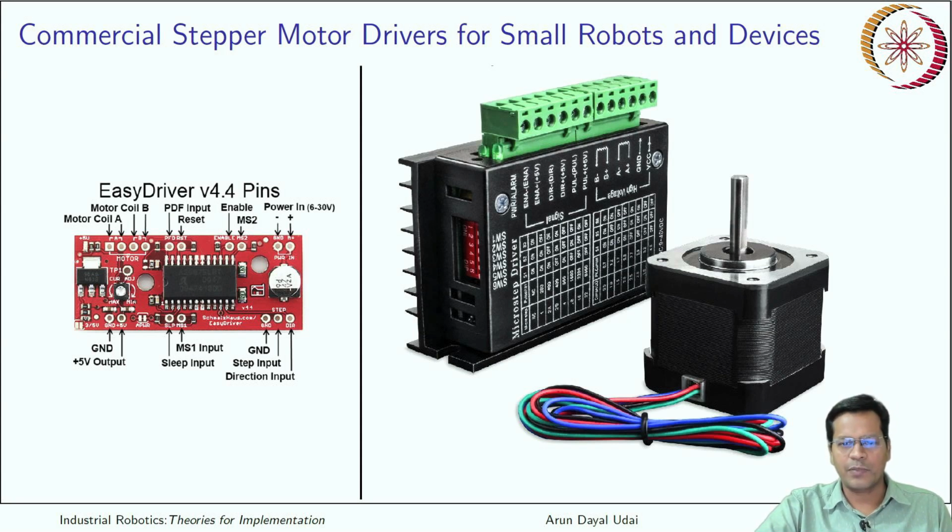It has some configuration switches which you can see here, and then you have an enabling switch that enables the motor. It has A bar, B bar wires which can be connected here. Sometimes these types of drivers already have a Modbus connection to address the stepper motor velocity and pulse signal.